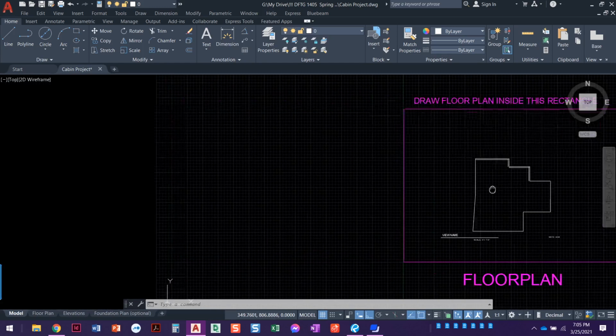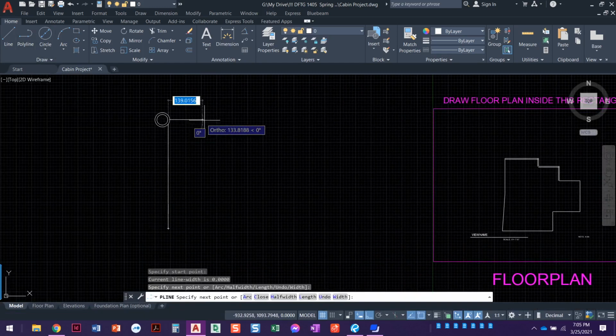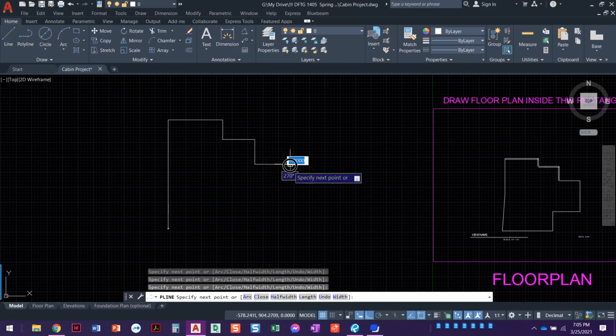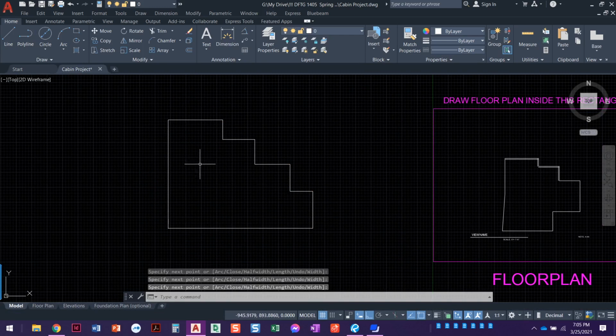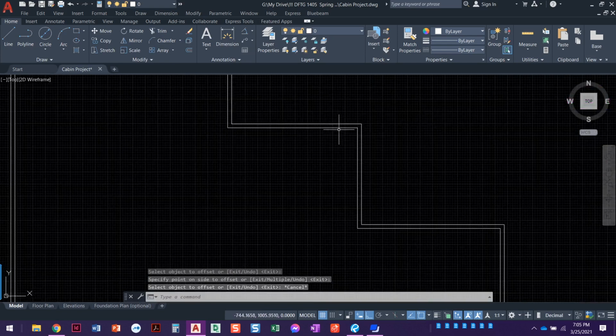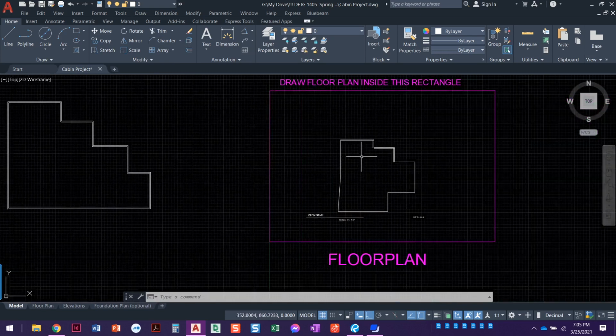I'm going to scooch this off to the side here, and I'll show you. We want to use polylines. So if I'm drawing out my walls, I've got my polyline here. This would be a really funny looking house. It's like a staircase. But the Polyline command is one long continuous line every time you click. So when we get started and I say offset, 4 inches, click here, go inside, look at that. Everything is perfectly clean. I don't have to trim, I don't have to extend. All of my walls just perfectly offset to the inside.